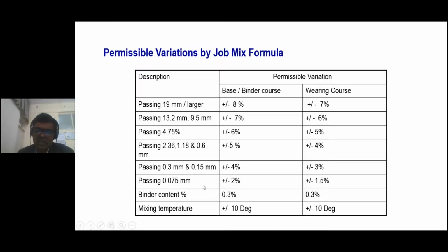And this, look at this. This is the tolerance. You can see in this slide what is the importance given for the gradation. If after construction, if we go and check, do the postmortem, take out the material and see, this is the tolerance. The gradation should not deviate from 1.5 to 8%. It is very, very difficult to maintain the gradation because we work in highly uncontrolled, adverse, rough conditions. But again, it is very, very important to maintain this tolerance within this.